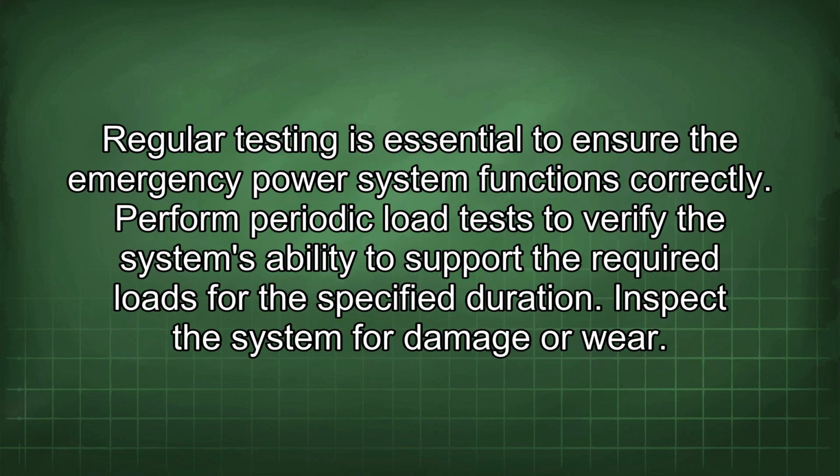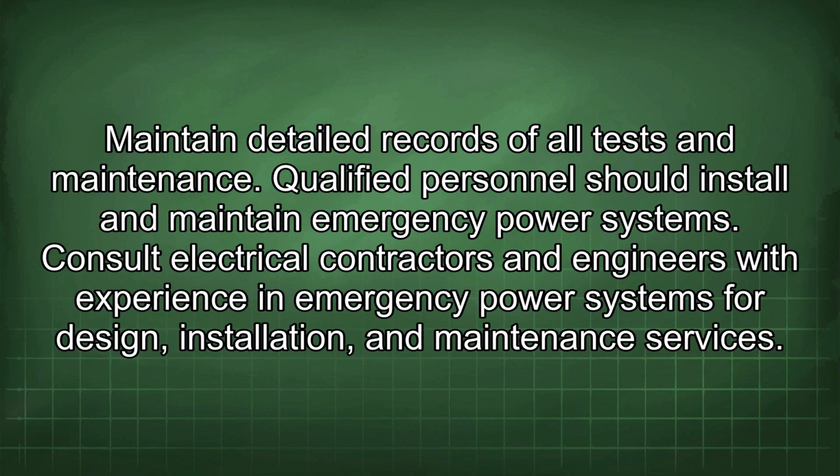Regular testing is essential to ensure the emergency power system functions correctly. Perform periodic load tests to verify the system's ability to support the required loads for the specified duration. Inspect the system for damage or wear. Maintain detailed records of all tests and maintenance.